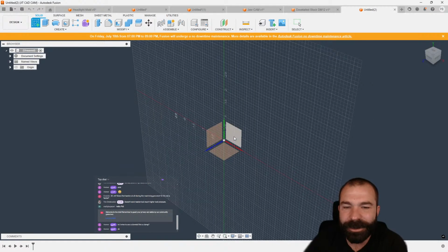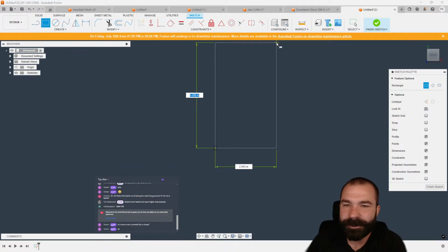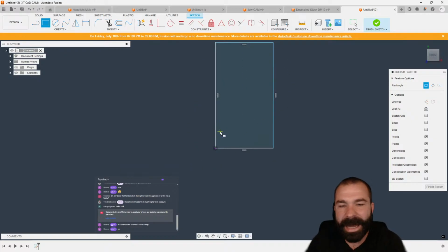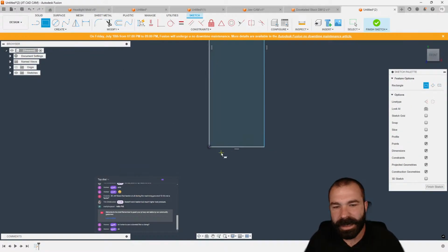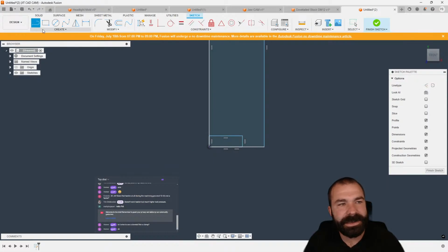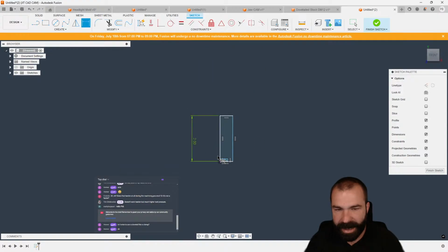It's a great way to look at that side of Fusion. As you guys are seeing here, I'm creating a sketch. I'm dropping a rectangle. Now, in my case, and this just might be me, I prefer to do a half profile. And you guys will see why here. So again, if I do a second rectangle inside there and a nice little line for my dovetail, as you can see, this total height is what controls our stock height.